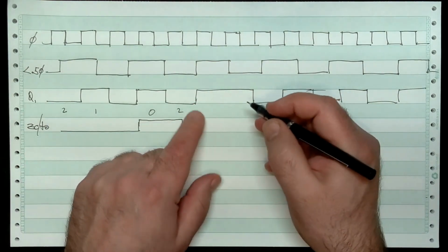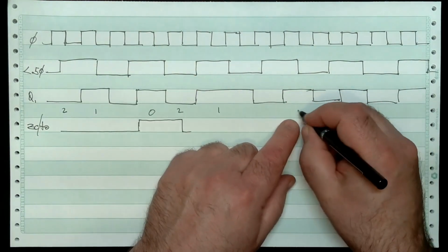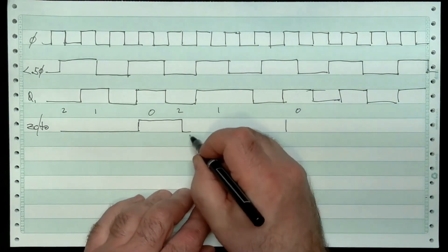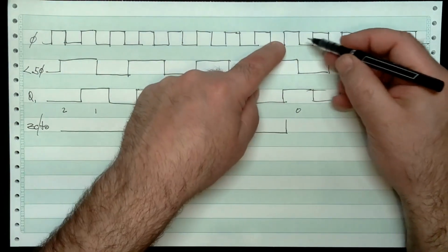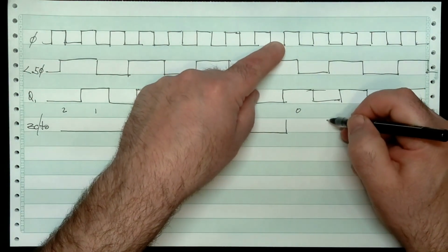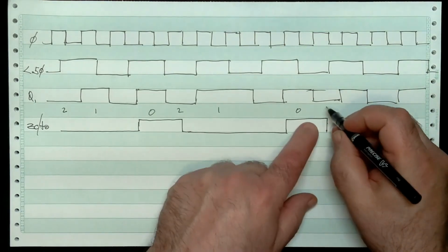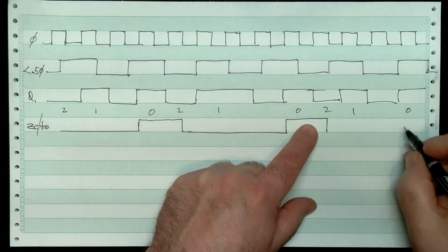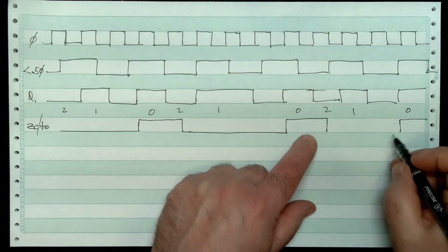So we end up with an edge here. This will cause it to go to 1, and this will cause it to go back to 0 again over there. And there'll be another pulse that comes out of here over there. And then it'll last for 1.5 periods, and it'll go low back over here. And then what do we got here? It gets reloaded with a 2, then it goes to a 1, then it goes to a 0 again. And there'll be another pulse here that will last a little bit longer than the sheet allows us to show here.